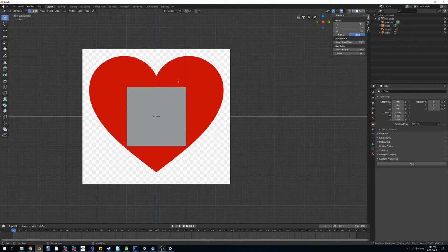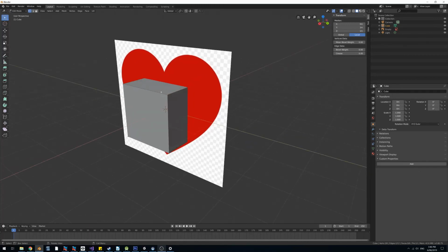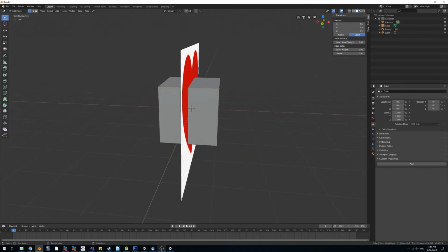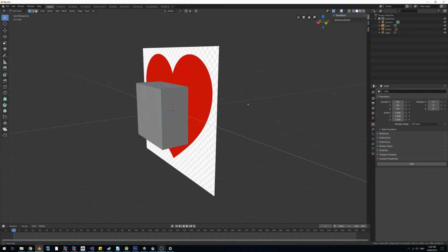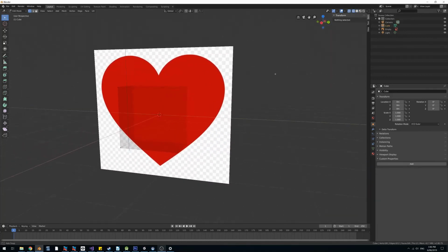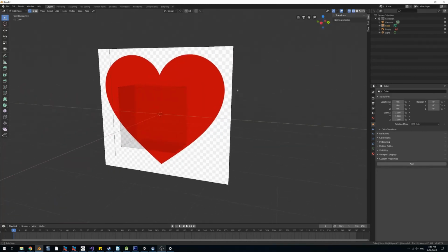So the next thing you might notice is that this is a grayed out box. And so if we're looking at this from both sides, this grayed out box will mean that when we try to select this particular vertex in orthographic mode, we won't be able to select any of the back-facing vertices. And that's a bit of a problem. So what we want to do is come up here and choose Viewport Shading to Wireframe. And so now we can see through the box and we can see all the way to the back vertexes that we want to select.